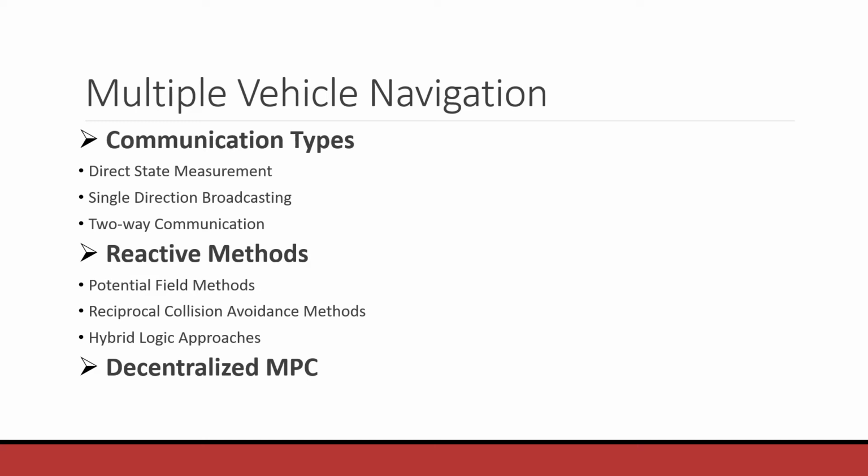Reciprocal collision avoidance method. Approaches termed reciprocal collision avoidance achieve collision avoidance by assuming that each vehicle takes some responsibility for each pairwise conflict, with the resulting constraint forming a set of viable velocities from which a selection can be made using linear programming. Some interesting extensions have been proposed to the ORCA concept.